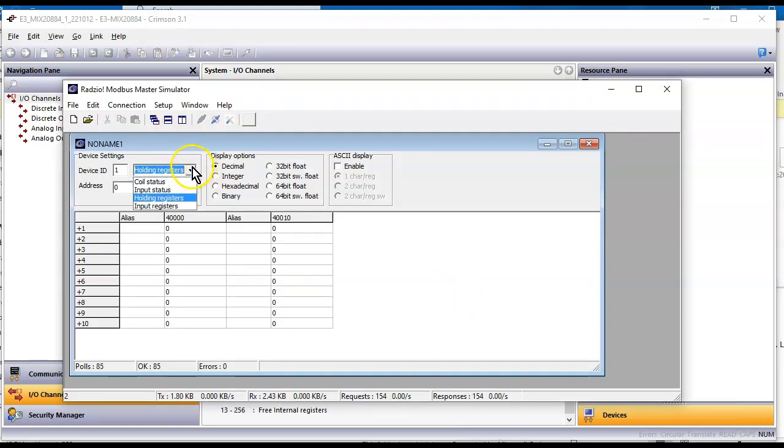Okay, so if we go here to our input registers, we got some weird number here. I don't know why that is right now. Let me turn on my 4 to 20 mil simulator again. Okay. All right, this is interesting. I'm putting out 0 milliamps right now. Look at that number. Let's go ahead and ramp this up and see if anything changes. Aha. Let's take it up to 4 milliamps. Hold on, I went way past it here. So I'm at 4.1 milliamps. There's that number.